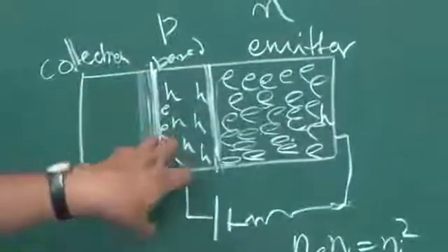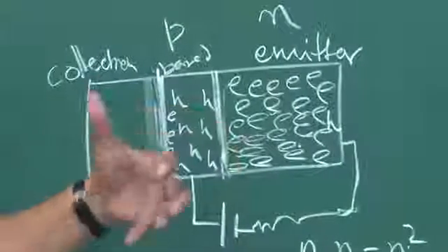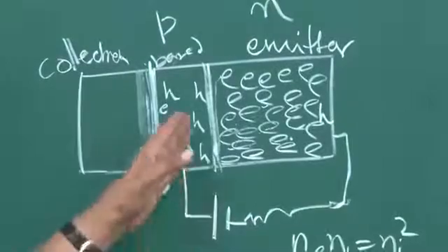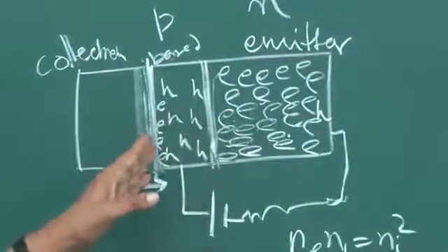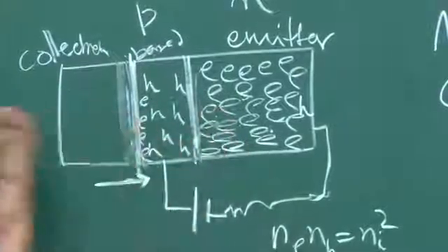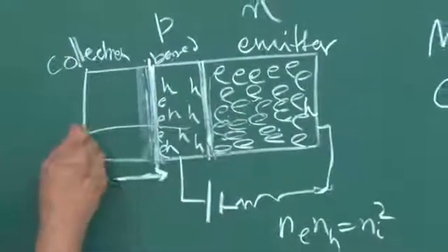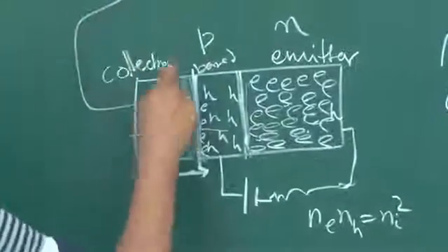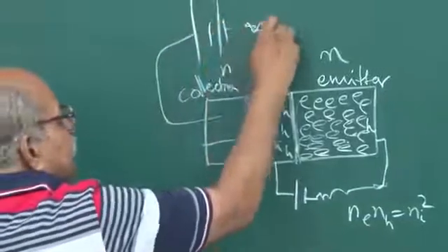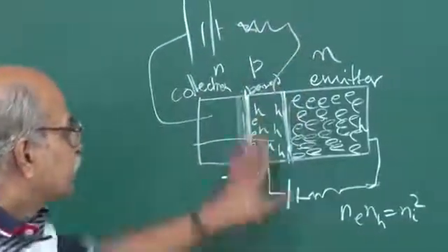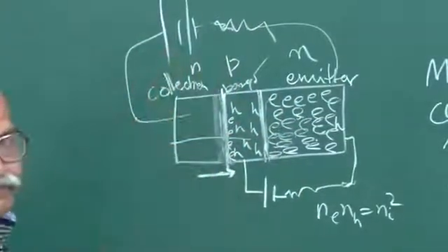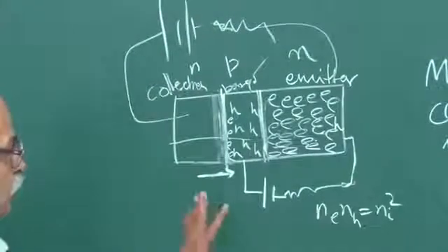And this electric field helps the minority carriers in making the reverse current, and therefore all these electrons which are crossing and reaching this depletion layer here where you have this field will be drawn towards this collector and will go to that biasing battery which is there. This is P, this is N, so you should have positive here, whatever resistances and all that. Okay, it's connected here, but anyway the potential difference is there, right? So what is the picture now?